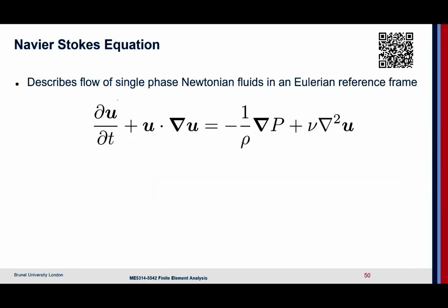From the Navier-Stokes equation, we can do the same thing. Let's say we're going to look at a steady state. There's no change in time. We're going to look at laminar flow, so low Reynolds number. Essentially, the convective term we can say is negligible. And we're going to assume there's no pressure gradient. There's no pumping. Again, don't worry too much about these various things. I just want you to understand that through this process of simplifying these complex equations, you can get these minimal equations.